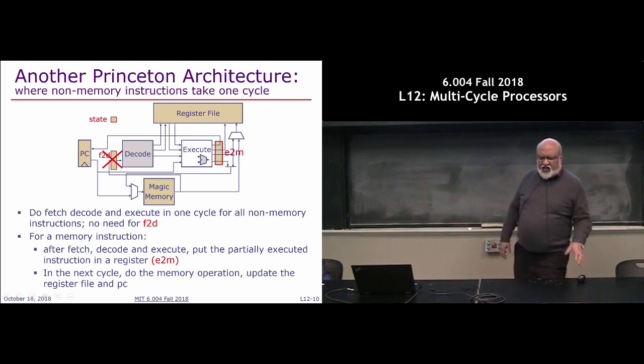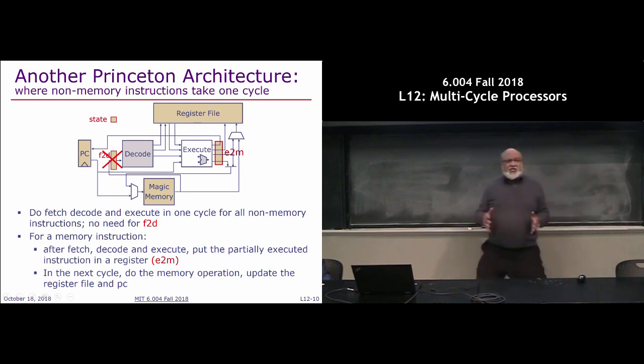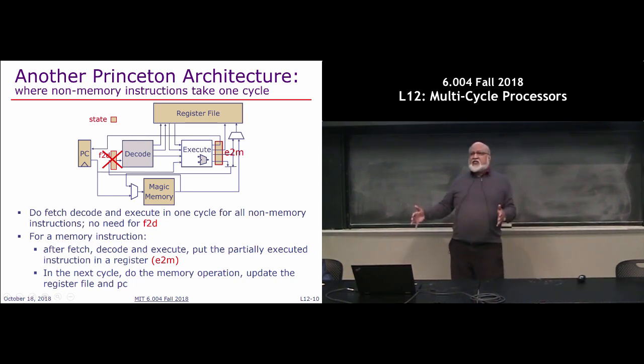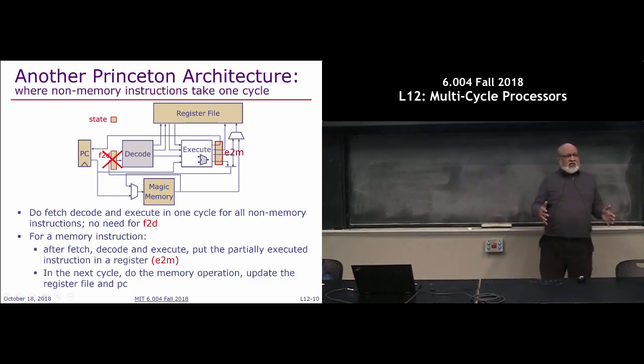That we were, until now, fetching something from the memory, taking our time. In the next cycle, we executed the instruction we had fetched. Now we are being much more aggressive. We fetch the instruction, we ask the question, are you a load store instruction? That question itself cannot be asked unless you have decoded it, right? If it is not a load or store instruction, you say, okay, just execute it. Update the register file, do everything, and go and do the next fetch.